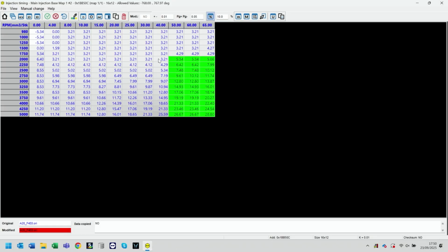And you'll notice on here, I'm going to go back to the 40 on the fuel. So I'm not going all the way down to this 30 point, which is typically our halfway point, equivalent to about 50% pedal. I'm going to our 40 millimeters cubed on the fuel, which is around about 60 to 70% pedal. Again, moving out of that normal driving, cruising area into more of the performance range of the vehicle.